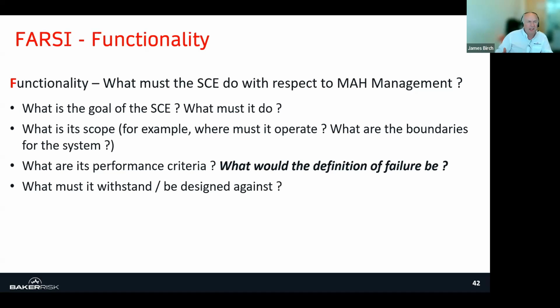And we'd need that to last for probably 90 minutes. So by setting those, we've now set the failure criteria that says, if our lighting does not provide that level of illumination in those key areas for that period of time, we have to say, we have a problem. Our safety critical element is not meeting its requirements. What are we going to do about it? And that's why the failure criteria are actually very important.